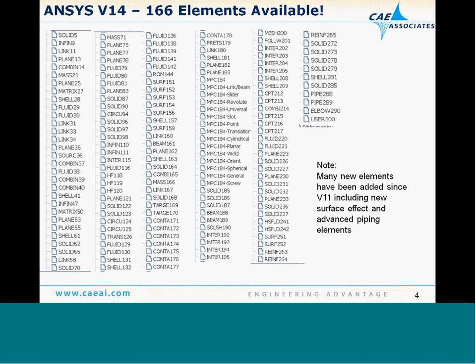A little fewer elements, but actually new elements have been added, and a few elements have been put into the archives. So with this number of elements to select from, what's the approach that we should use as a user to determine which is the best element type to use for my particular application?